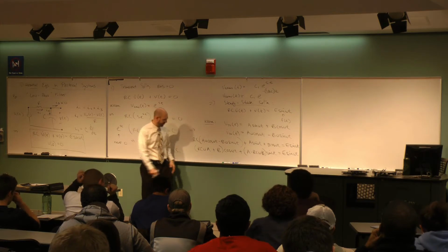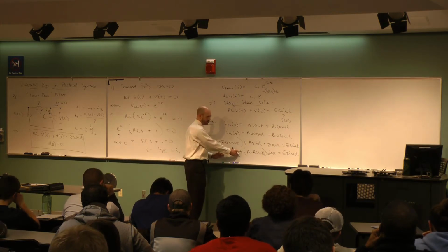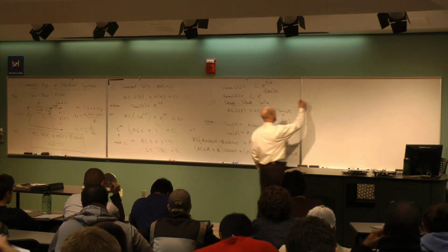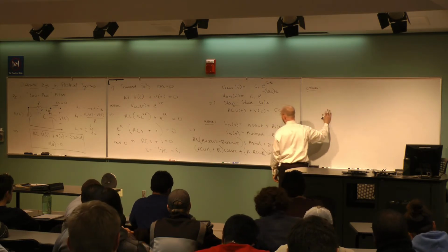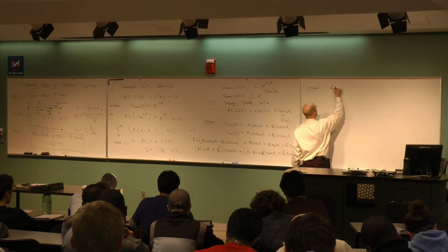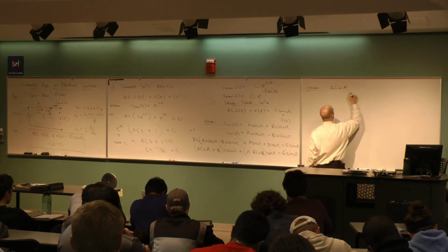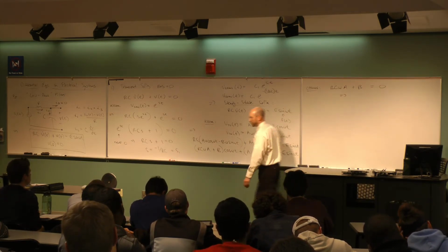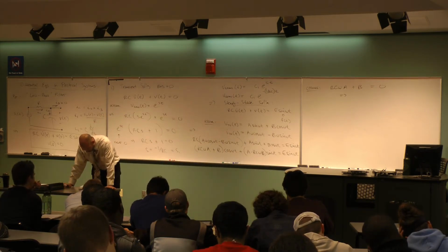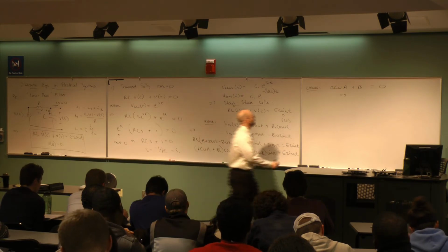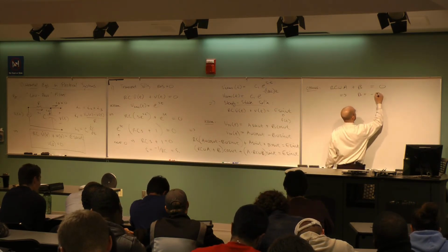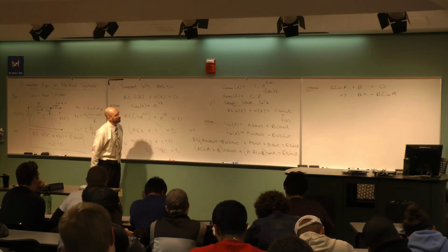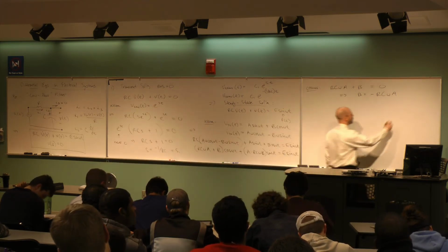I compare the coefficients. Something times cosine on the left. What's multiplied by cosine on the right? 0. Nothing. Okay, so if I look at the cosines, that's the first set of coefficients. Then whatever's on the left better be 0. RC omega A plus B has to be 0. So right away, I ought to be able to solve for either A or B in terms of the other one. And so I'll solve for B. This means that B has to be negative RC omega times A.